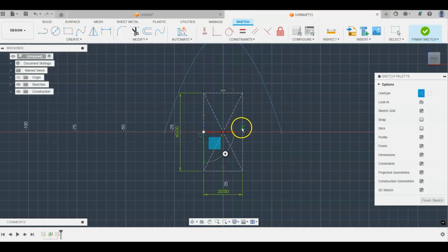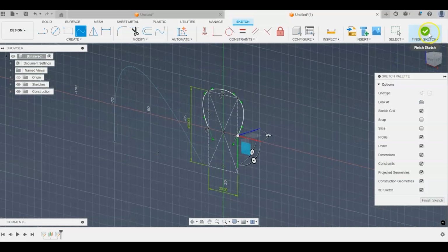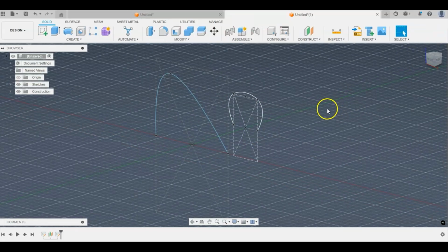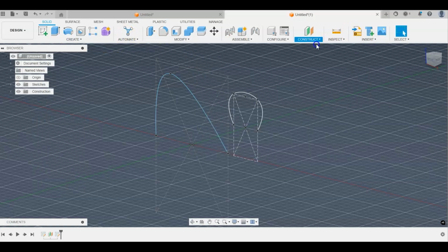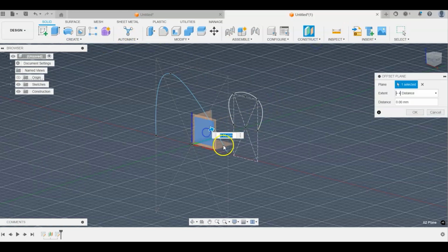And so then we now have some points there, and I'll create a little point. So I have a point there on that one, a point there, and we have a point there. We can also create some more points on the corners as well. Okay, so anyway, I'll draw a little sketch from here. We're turning off construction line, back into real drawing mode. One up there, and then one back down there. And close that one. So we have a sort of shape there now. And finish that sketch.